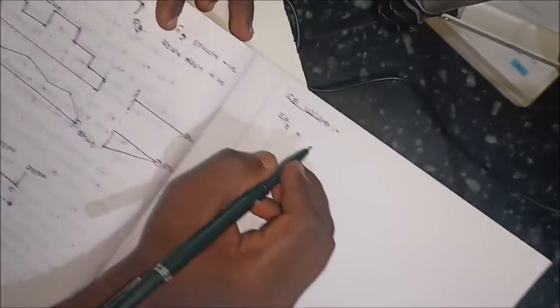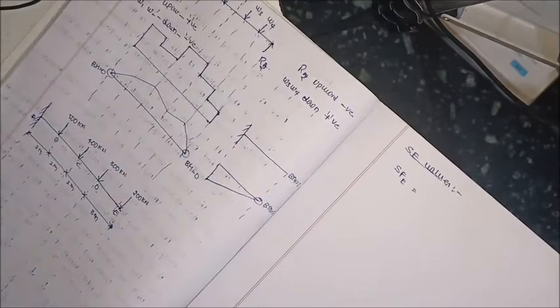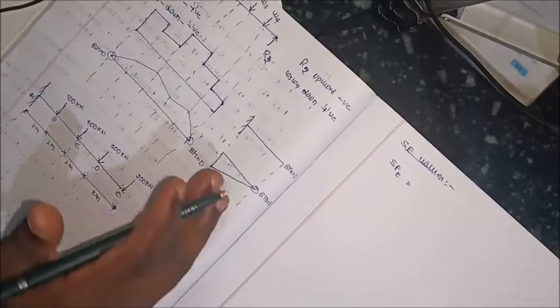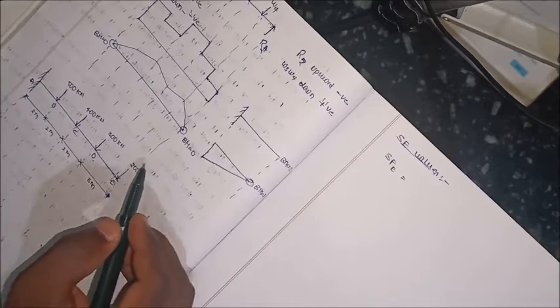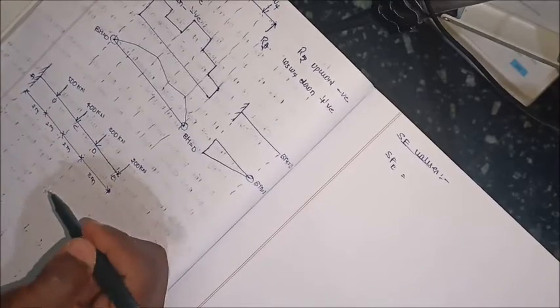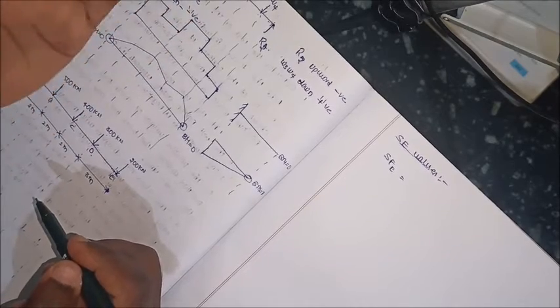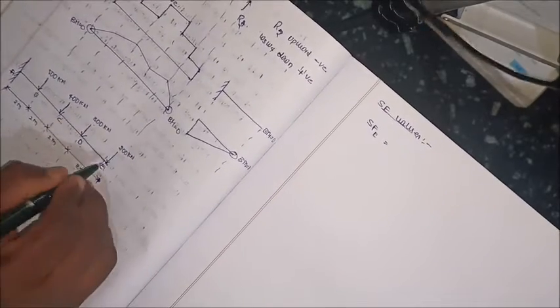So calculate the shear force values. Already we know the shear force sign convention, either positive or negative. While considering the section, if choosing the right of the section, the upward forces are negative and downward forces are positive. If the section is chosen with the left portion, the downward forces are negative and upward forces are positive. Here to consider shear force values.